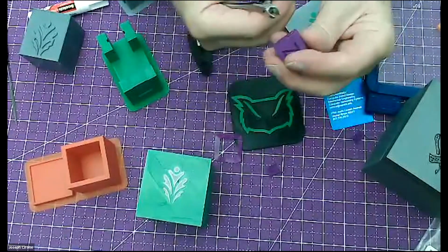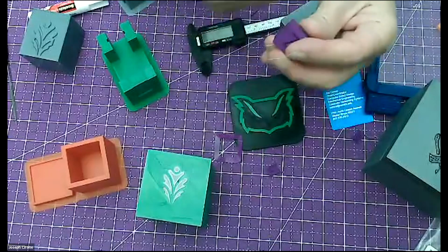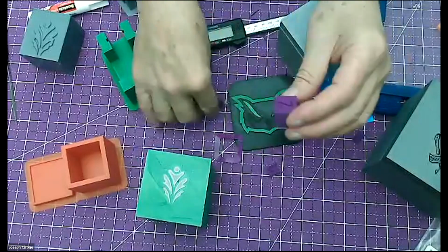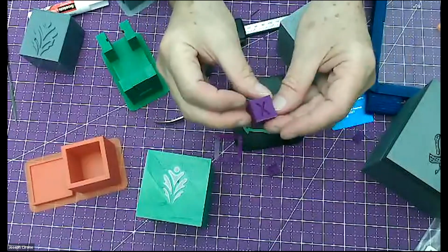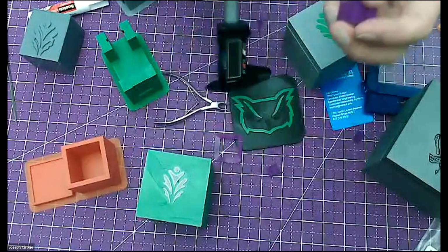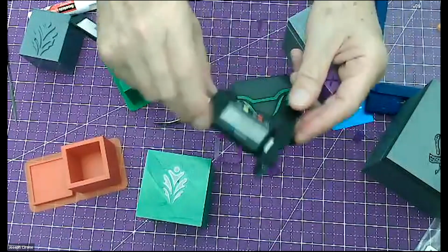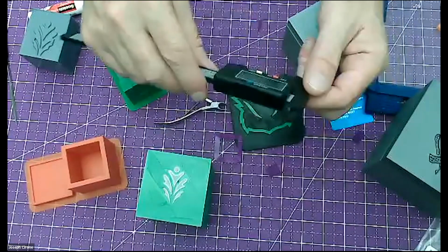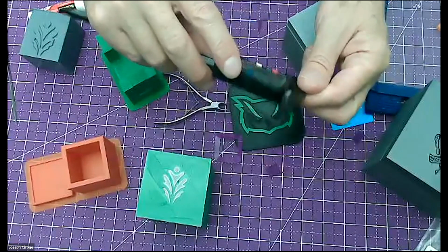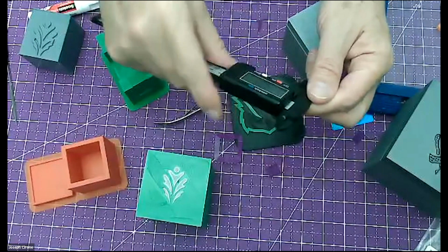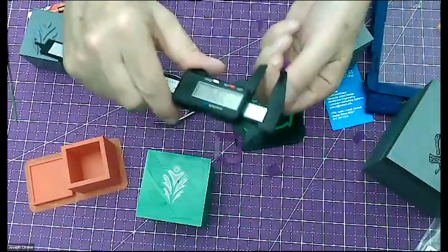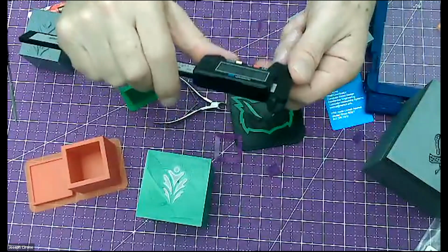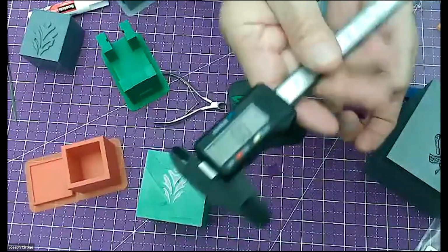What I'm doing nowadays is that I need to calibrate my 3D printers every month. This has a Z, an X, and a Y axis on it. Then you print it every month and you take your micrometer or calipers, making sure you have it set to the proper units. So I'm going to switch this over to millimeters, and then make sure that your blades don't have any material.